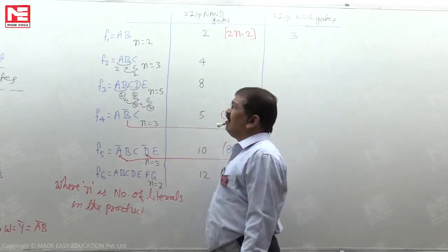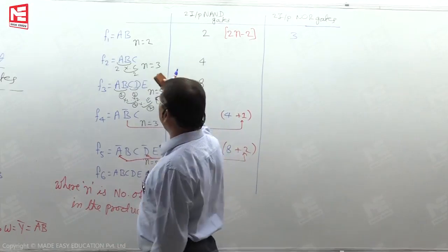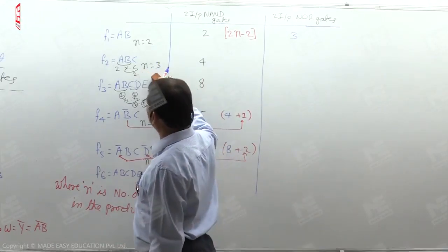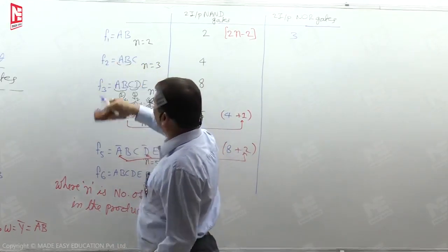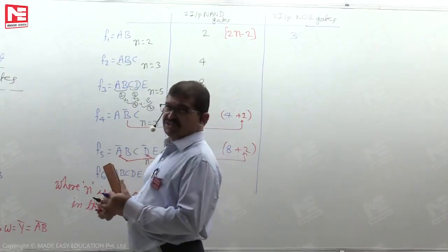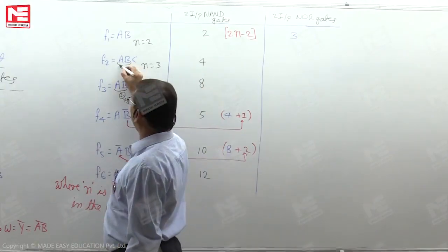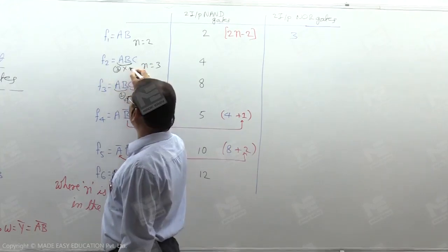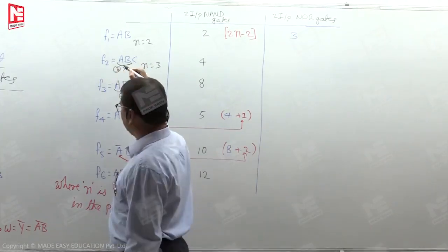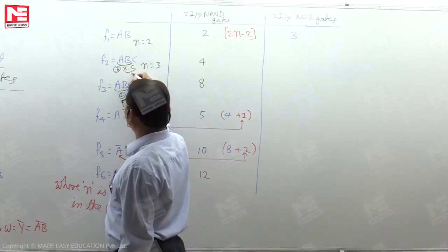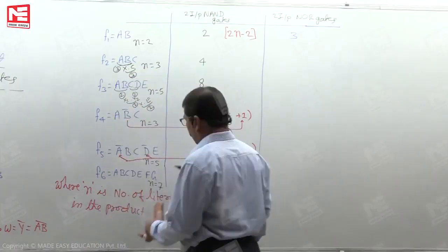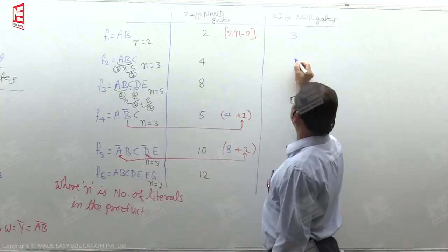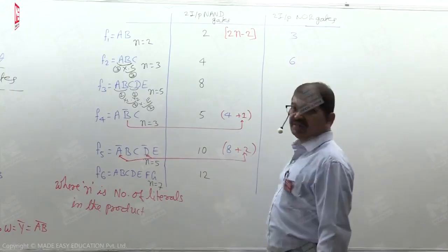And for the implementation of A and B and C, similar to the previous case, for AB purpose we need 3 gates. If I name the result X, then X and C needs 3. So 3 plus 3, we need 6 gates here.